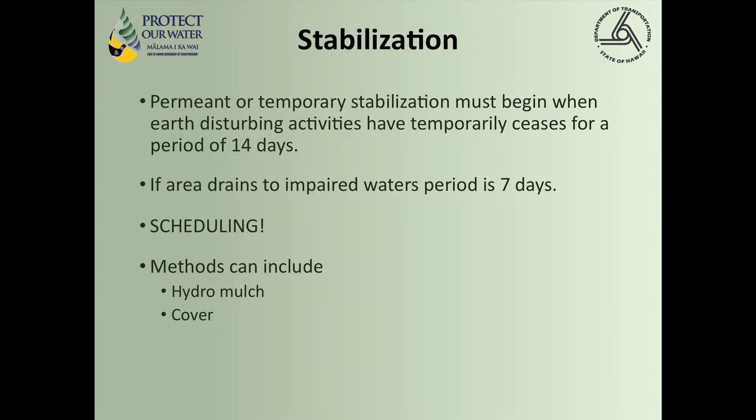That does not mean at day 14 you go out and run a piece of equipment up and down. That doesn't work. Active construction. If you're not going to work it, you need to start temporary stabilization, and we will cover several methods of that. But two here are listed: hydromulch or cover it.